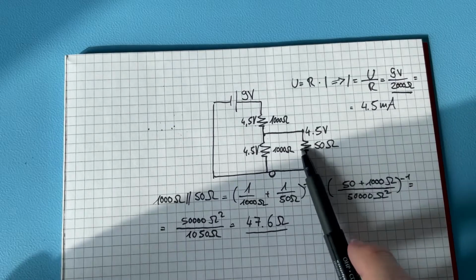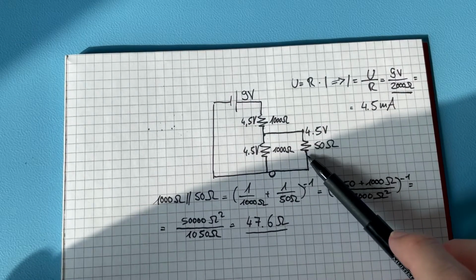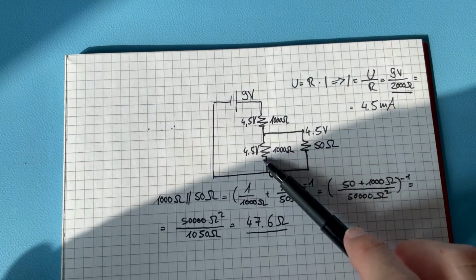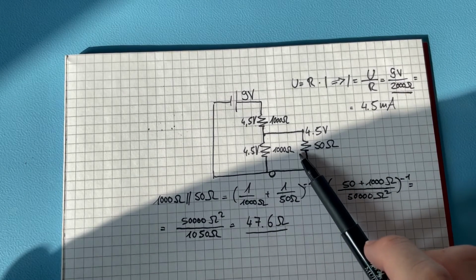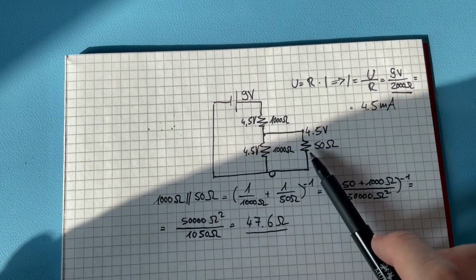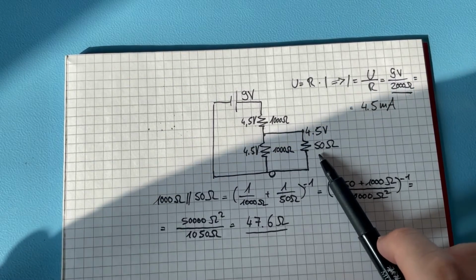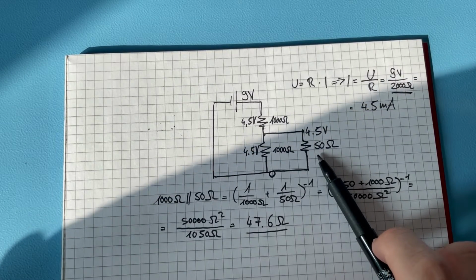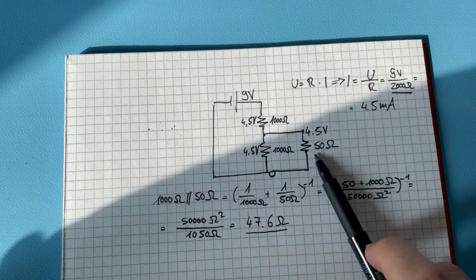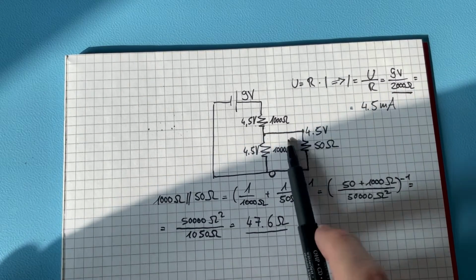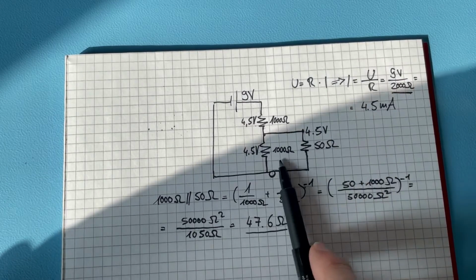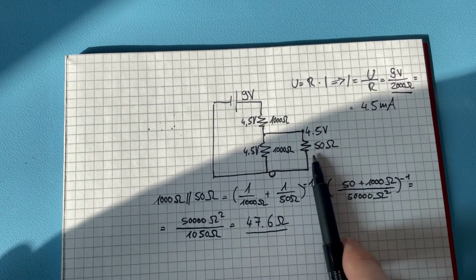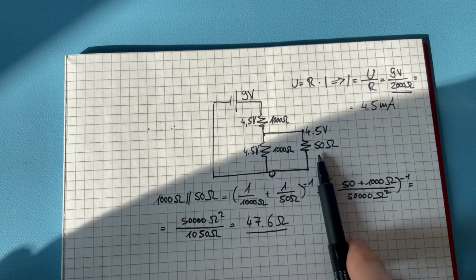And that's the general rule. You also can remember in a parallel circuit, if you look at parallel resistors, then that parallel construct always has a lower resistance than the lowest resistor you can find in the parallel construct. So 50 ohm was our lowest resistor, and no matter if there were additional parallel resistors here, we are sure we're going to get lower than the lowest resistor.